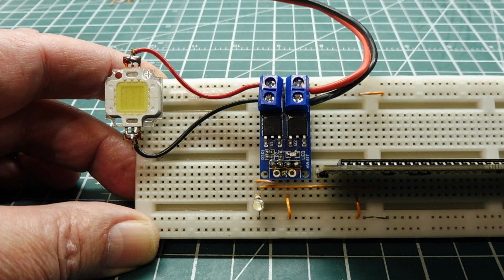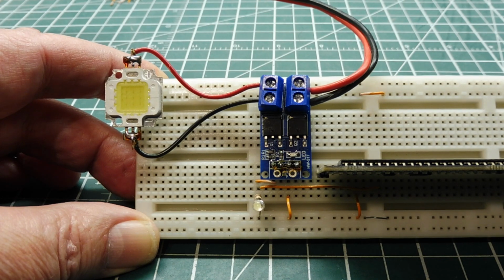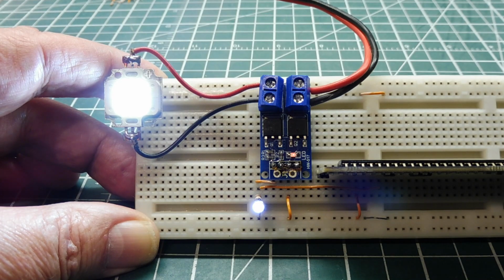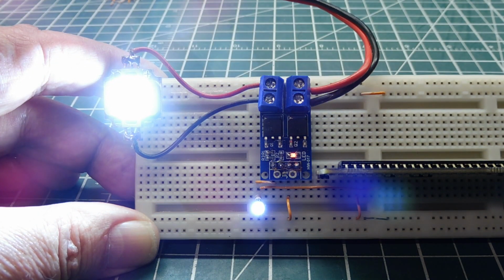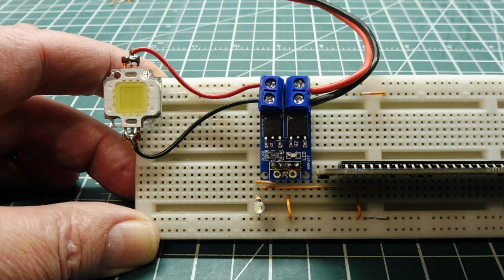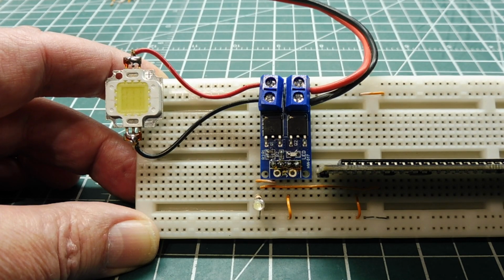Okay, I have a high intensity LED connected up to my MOSFET driver, and it's being controlled with my Scamp3 board, my PWM output on pin 2. So if I use my keyboard and I'll give it 1%, so that's 1% duty cycle PWM, and I'll bring it up. It's going to get bright, so I'll take it right up, all the way up to 100%, and I'll take it back down to 0. So that's how we can control some heavy loads using PWM using the Scamp3 board.